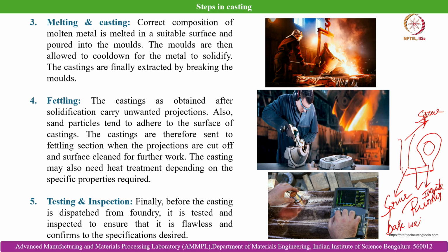These are the functional parts during the feeding of the liquid melt, because they cause preferential melt flow within the component cavity that we are intending to cast. But once the solidification is done, then only our functional part remains, that means the solidified component. So these all three parts need to be struck off. The process of machining them out after the casting is done is called fettling.